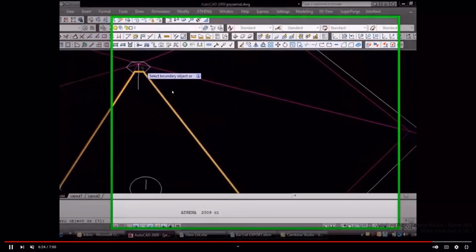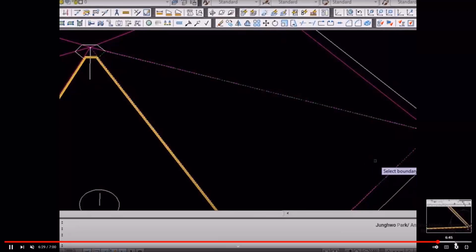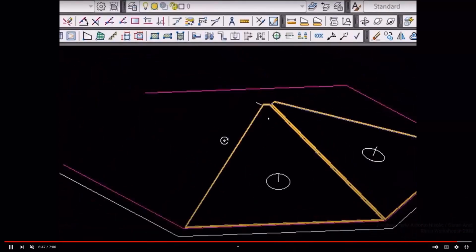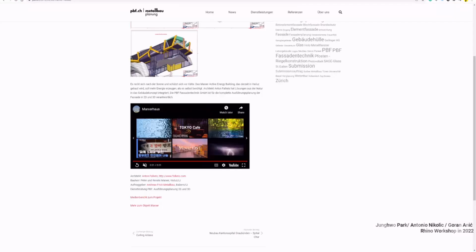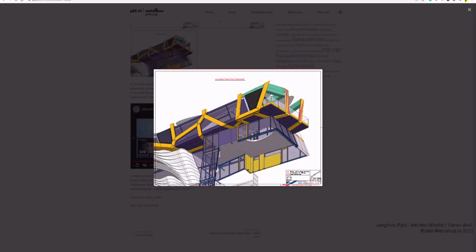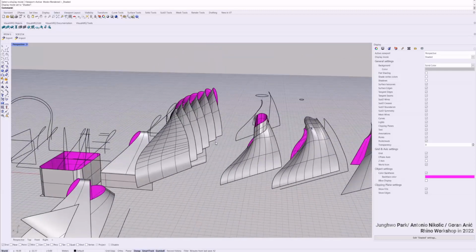It's based on your CAD detail and creates a really final detail, and then eventually you can export as an IFC file directly from this software and link into Revit. I think that's how we worked in this particular project, because it has really LOD 400 details, a much higher level of detail. All right, anyway, so Rhino can be very useful for complex projects.